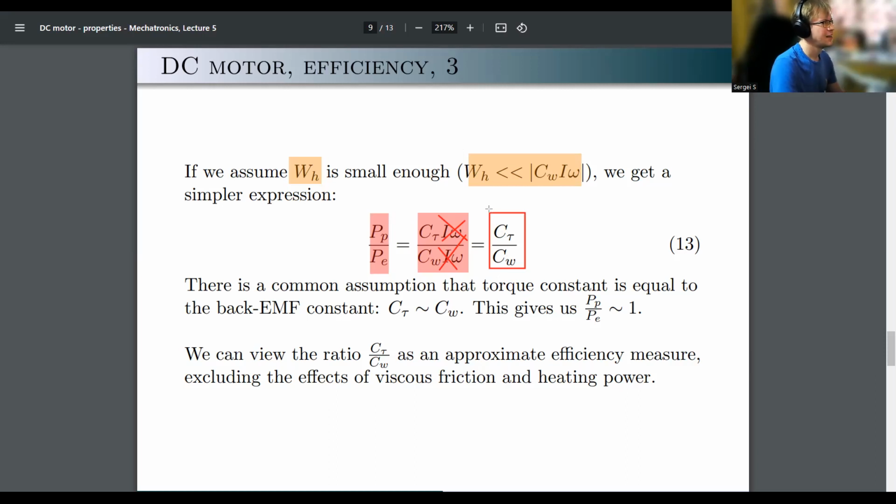Okay. So somehow the back EMF coefficient is equal to the torque coefficient. Who would have thought? But from power, you can understand what's going on. So often when people model motors without concrete knowledge, they just want to play around with numbers. They would assume that those two numbers are the same. That's a typical assumption.